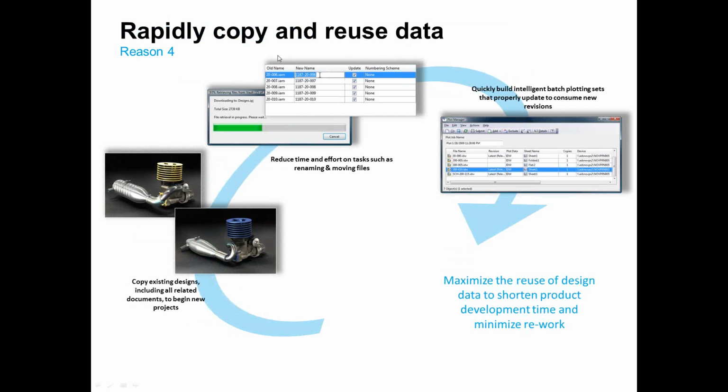The copy design is probably not a major feature in the civil area. One feature that is in the higher levels of Vault that's notated on this particular slide, which can be a benefit, is batch printing and batch plotting, which Vault Workgroup and Professional have. So at the end of a project, you can batch print all of the CAD drawings for a project. You can also include other file types as well, Word documents, PDFs. They can be in the batch. You can also select a folder, and it'll do all the files in a folder. And it's smart in that for each DWG file, there's probably a rendered DWF. The batch plotting can just automatically grab those since they've already been pre-formatted and pre-published and are a smaller file.